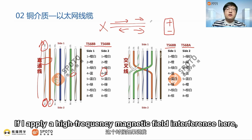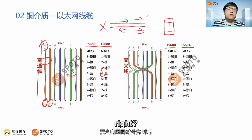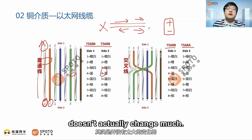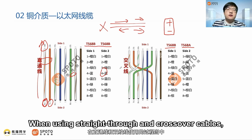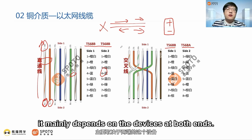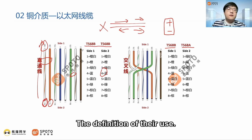If I apply a high-frequency magnetic field interference here, at this time, either both voltages rise together, or both drop, and the voltage difference between our two wires doesn't actually change much. This provides an anti-interference effect. So, when using straight-through and crossover cables, it mainly depends on the devices at both ends. It depends on how these 8 wires are defined for use in the twisted pair cable, the definition of their use.